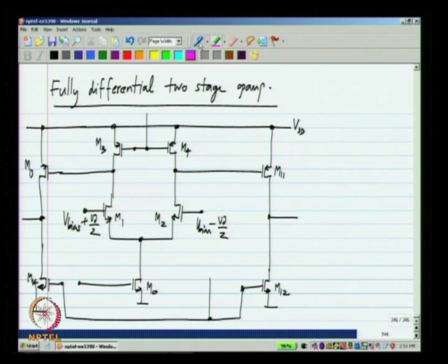So, we can start with making the single stage fully differential op amp with common mode feedback, that is I will show this as a box here. This box includes common mode detection and feedback, and the feedback as you know finally comes to the gates of M3 and M4. Okay. Now, we will look at the details of this, but the common mode feedback circuits that we have discussed so far will work perfectly well. So, now the output common mode of the first stage is stabilized.